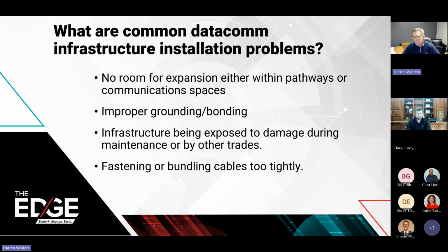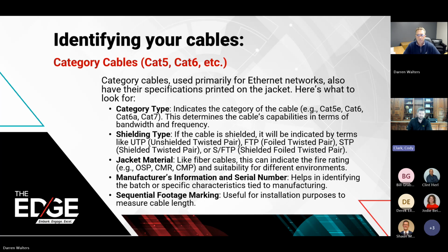We try to use the Velcro straps as much as possible to put the least amount of strain and pressure on that cable bundle as we can. Yeah, and those top three items, if they're not done properly at the beginning of your installation, they're inevitably going to cost you a lot of money down the road. So it is better to do it up front correctly.